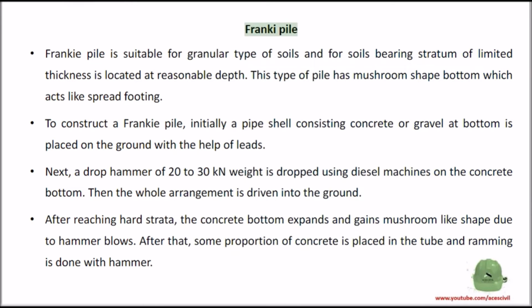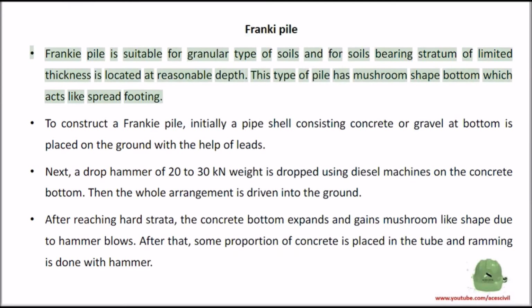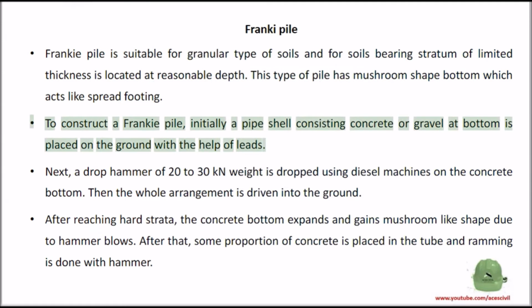Franki pile. Franki pile is suitable for granular type of soils and for soils where a bearing stratum of limited thickness is located at reasonable depth. This type of pile has a mushroom-shaped bottom which acts like a spread footing. To construct a Franki pile, initially a pipe shell containing concrete or gravel at the bottom is placed on the ground with the help of leads.